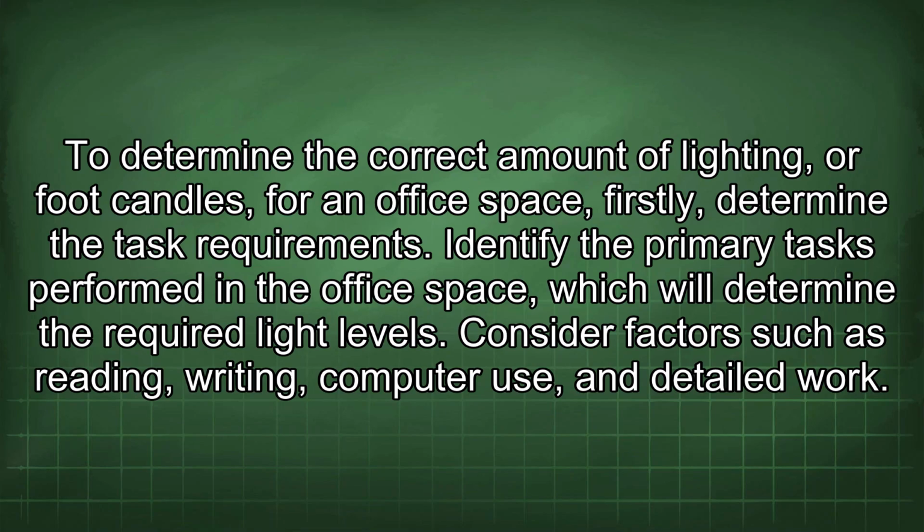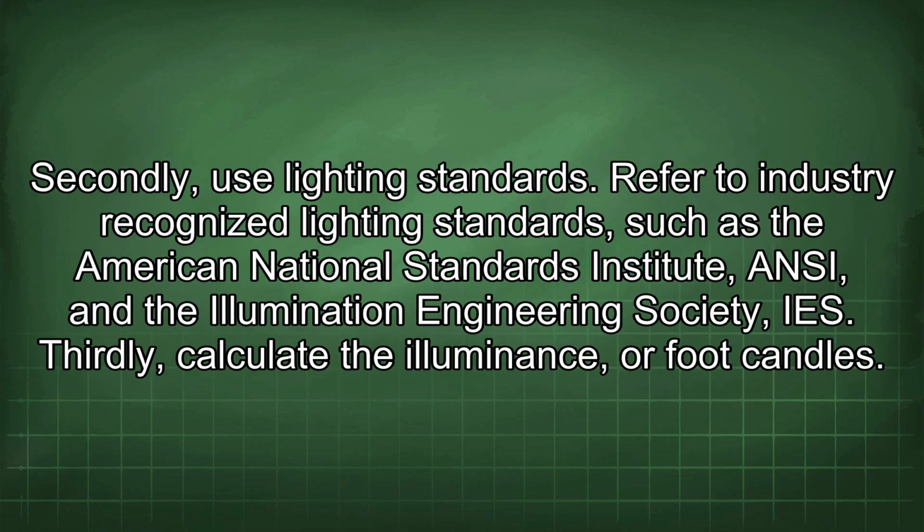To determine the correct amount of lighting or foot candles for an office space, firstly determine the task requirements. Identify the primary tasks performed in the office space, which will determine the required light levels. Consider factors such as reading, writing, computer use, and detailed work. Secondly, use lighting standards. Refer to industry-recognized lighting standards such as the American National Standards Institute (ANSI) and the Illumination